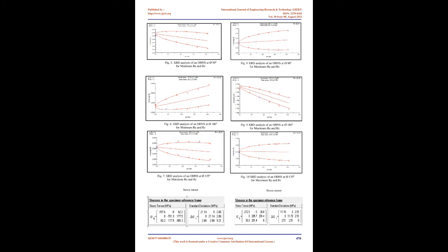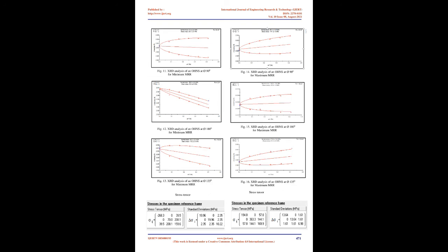Thus, the increase in work speed results in better value of RA and RZ with higher metal removal rate of 0.34 gms/sec. It is clear from the above graphs that as the speed increases from 300 to 350 rpm the value of RZ decreases from 1.48 to 1.32 µm. Though the increase in the feed increases the RZ value from 1.32 to 1.5 µm. The RZ value decreases from 1.52 to 1.32 µm as the number of passes increases from 6 to 8.